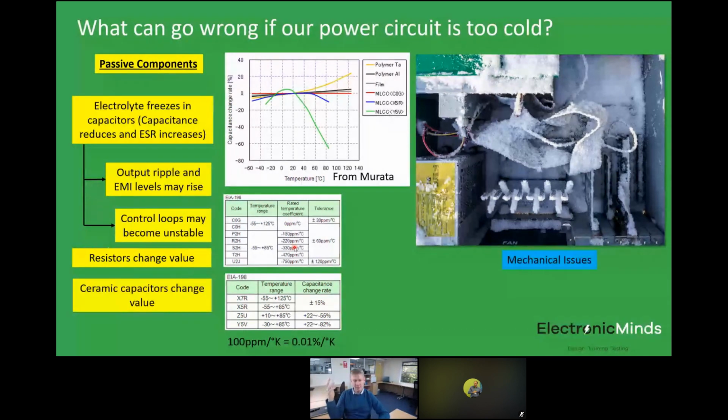If you have a liquid-cooled high-power converter system, down at low temperature, those liquid coolants that are flowing through the circuit can either become very viscous or they can actually freeze. And that creates a really obscure problem in that when you first power up a high power converter with liquid coolant that's frozen, you can't get the liquid flow through the cold plate and out to the heat exchanger. So actually, even though it's down at low temperature, you can't cool that power converter properly.